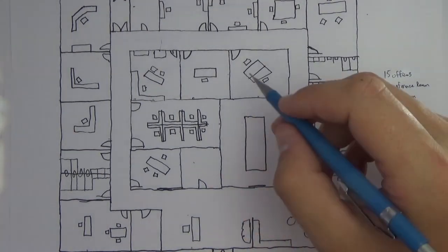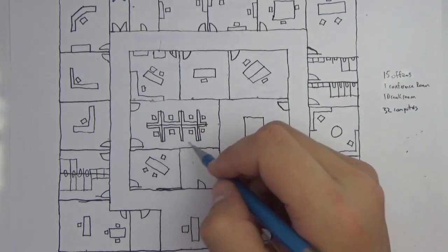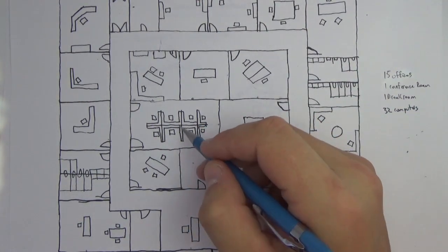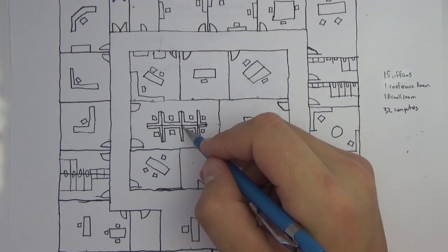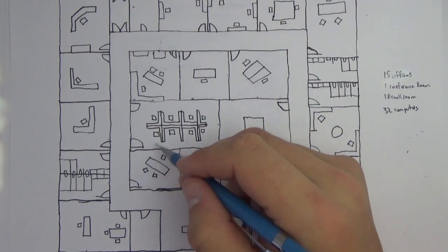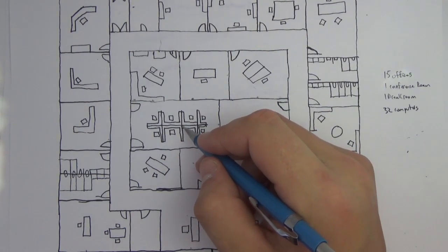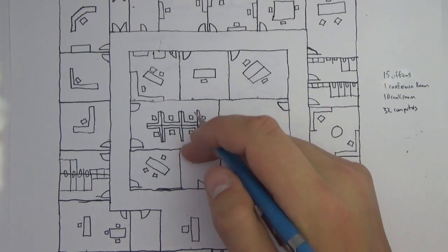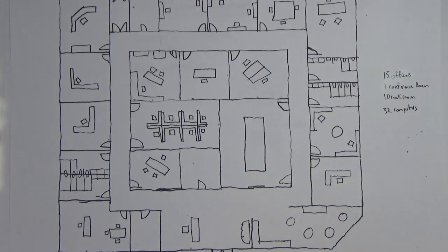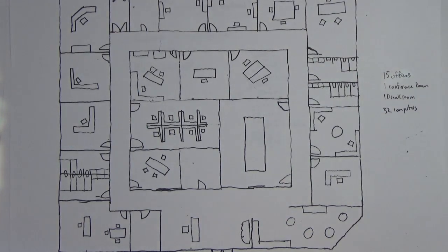Again, very rarely do we actually want to come up through the floor in the middle of the room. If this is a cubicled office, it's possible that it might not be a bad idea to bring it up through the floor in the middle of the room. But if they ever decide to switch the cubicles to face the exterior wall rather than all facing the interior of the room, all of a sudden we've got the same problem: those network drops are not very conveniently placed. So think through the traffic for these wired runs. Where do we actually want to put stuff so that we can get wired runs? Now that's coming up from the basement.